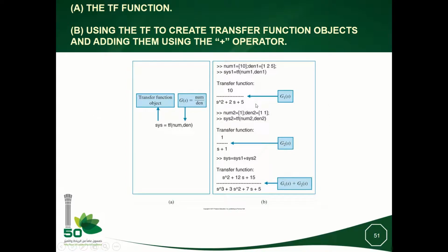So here I am creating two transfer functions, Sys1 and Sys2, using the numerator and the denominator. It means the coefficients of the polynomial of the numerator and the denominator. I can then construct system 1 by the instruction TF, numerator, denominator. So I will get this transfer function. I will do the same for this. So I have two different transfer functions.